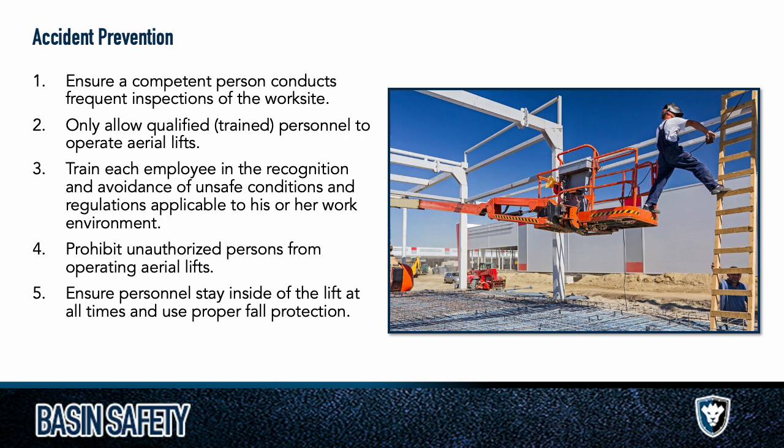Rebar below. Don't get me wrong, he's not 100 feet in the air, right? He's probably 8, maybe 7 feet in the air. But if you fall from that height, people die or get seriously hurt falling out of the back of pickup trucks every year, right? They get up there, start moving stuff around, fall out, and literally they don't make it. It does not take a lot of height, even on flat ground, to get hurt. So in this situation, just a lot of things can go wrong. He's not tied off. Even if he was tied off, this would be a bad situation. It would swing you right into those. This might be a bad situation to be tied off to the aerial lift at this point, actually. But ultimately, 100 things going wrong here, and we're going to check those off the list as we go.